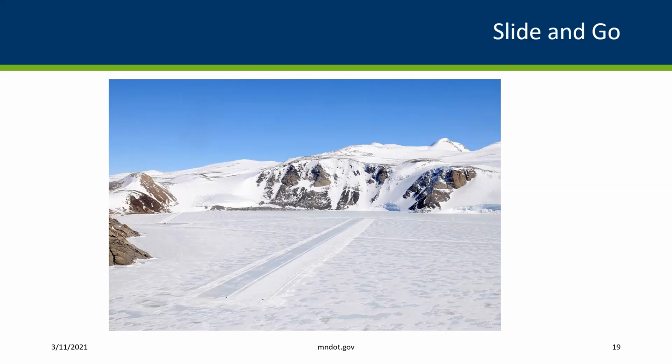We attempted contact with the airport manager. We were unable to make contact via phone messages and emails. There were no snow events in the few days prior to us going on this trip, and the day of the trip, it was absolutely beautiful weather. So the other crew member and I planned the trip. We did our due diligence to try to make contact. We looked at the NOTAMs, and there were no NOTAMs indicating any contaminants on the runway. If you don't say that you have something on the runway, the FAA defaults that to there's nothing on it. So that was our perspective going in.